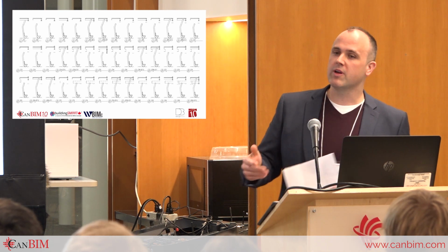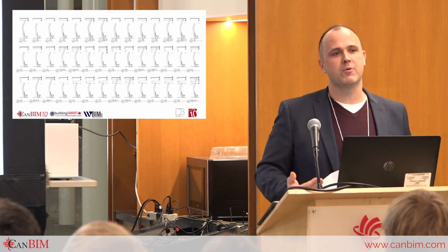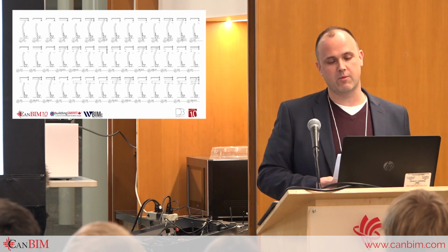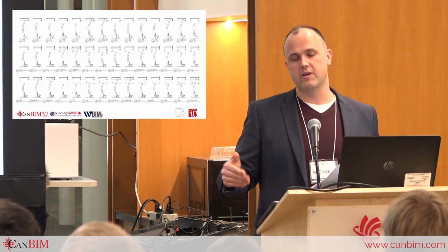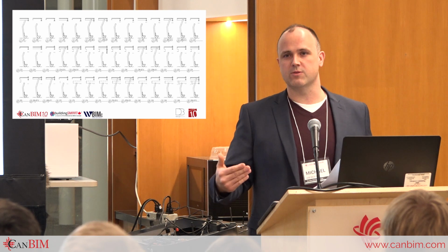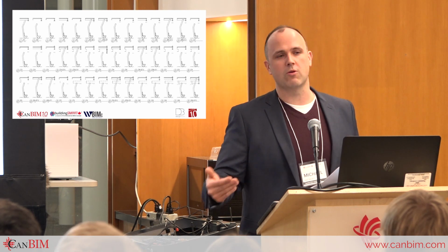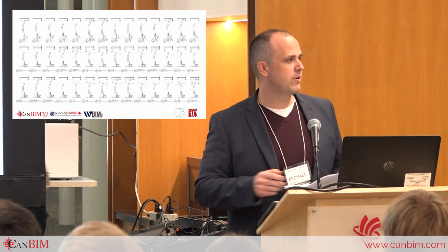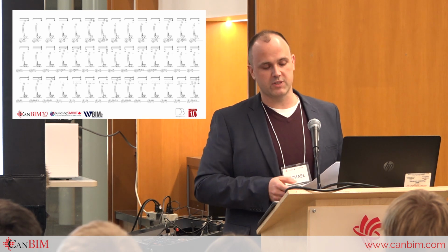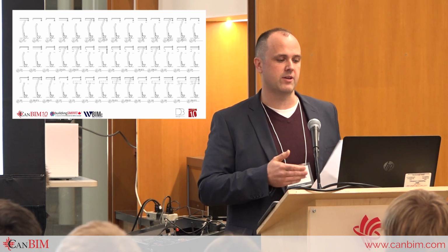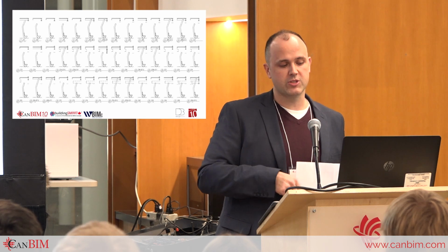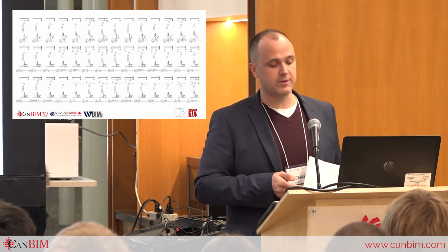But as we were working through this with Design Built, we realized that plywood wasn't really something that we wanted from a material perspective, because each of the edges of the fins was going to be exposed to the corridor traffic, which was heavy use. We were worried about damage over time. And so we thought, how are we going to approach this with solid wood?